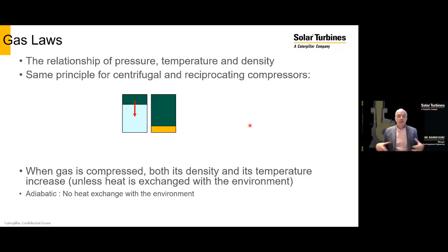So essentially, the general idea is if I trap gas in a certain volume, and then I reduce the volume, then I will increase its density, but I also will increase its temperature unless I cool that cylinder, meaning unless heat is exchanged with the environment.